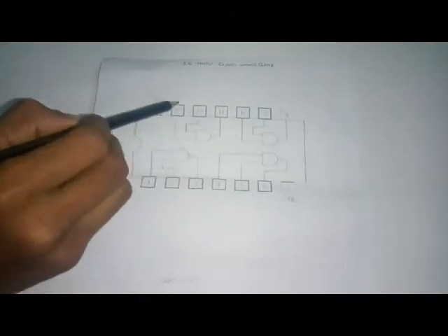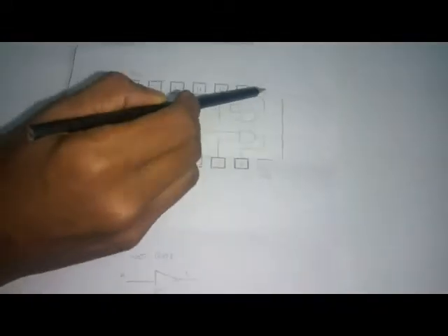This is the pin diagram of IC7400 quad NAND gate. Here we can see that as all the ICs, this IC also has 7th and 14th pin as VCC and ground pin. And the input pins for the NAND gates that we are seeing here are 1 and 2, 4 and 5, 9 and 10, 12 and 13 respectively, and the output pins are 3, 6, 8 and 11 respectively.